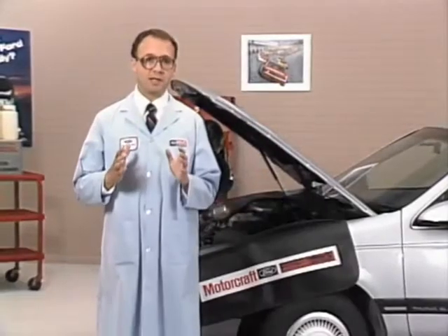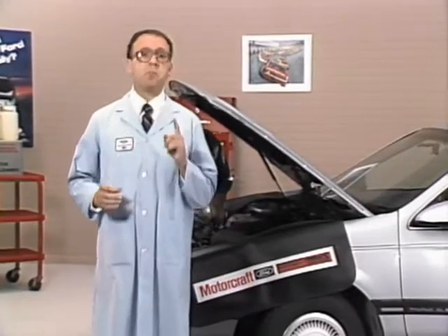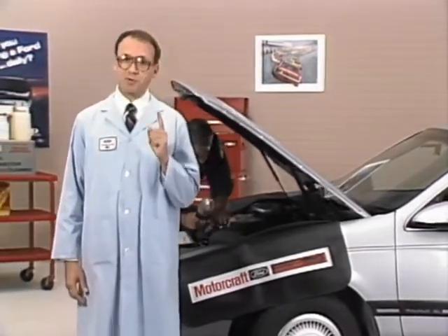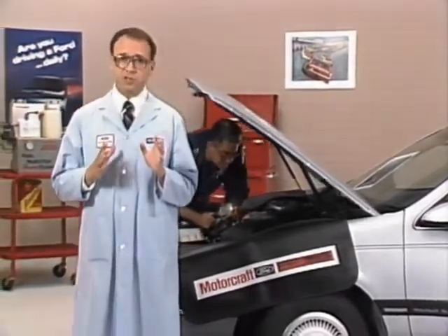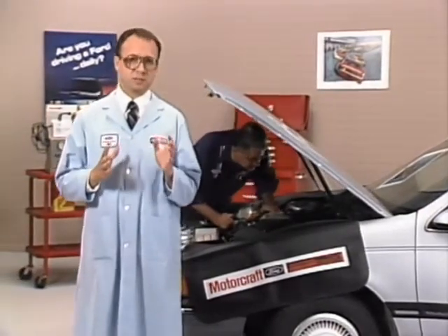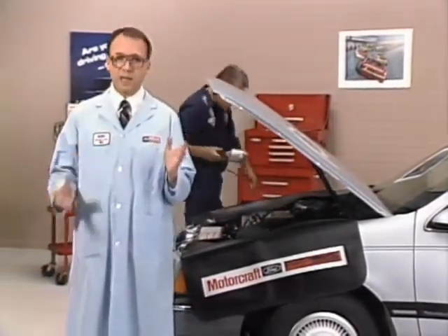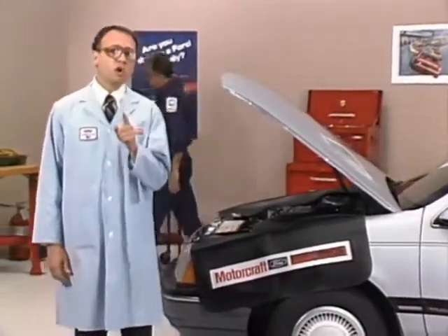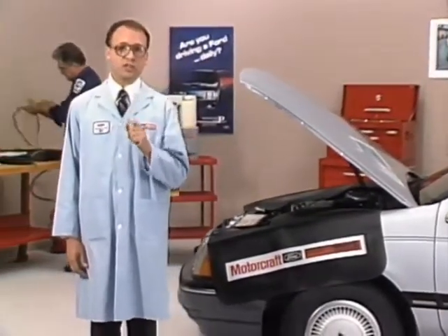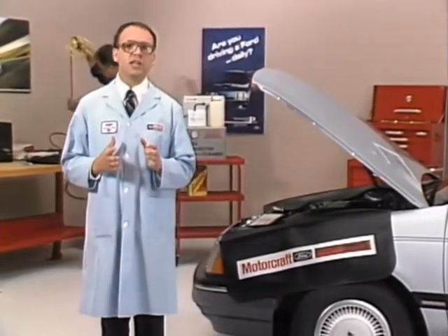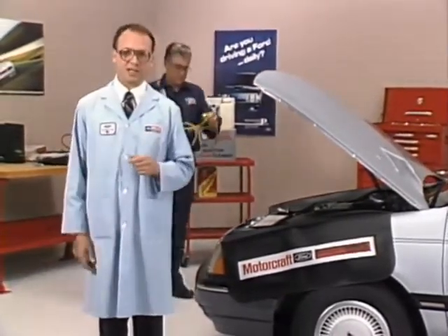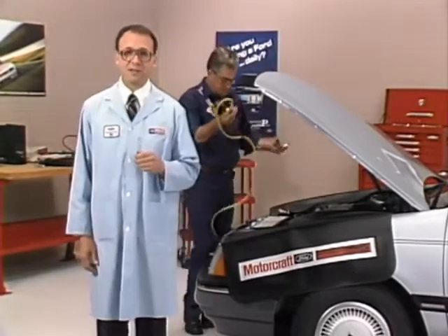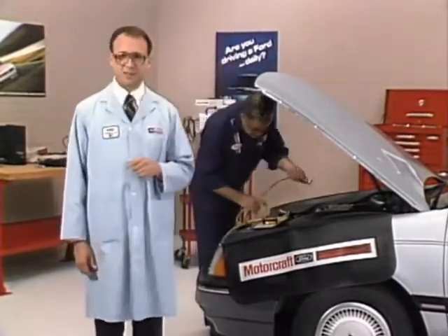To operate properly, the fuel injection system must maintain a specified operating pressure. Insufficient fuel pressure can produce symptoms ranging from no start to lack of power, depending on how low the pressure falls. So, your diagnosis of the fuel injection system will often include checking system pressure with a pressure gauge. The pressure check isn't difficult, especially on a vehicle like this one.